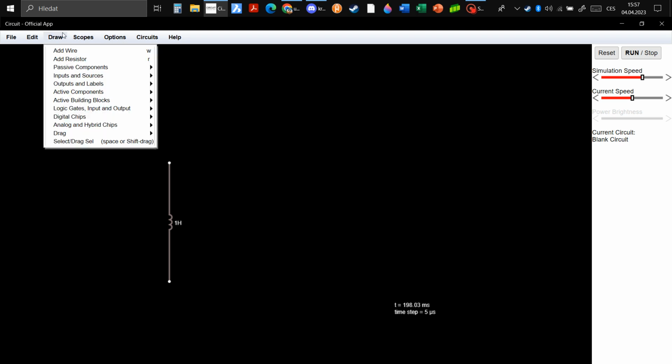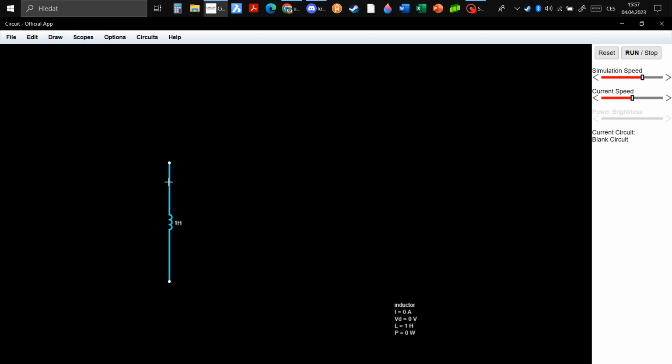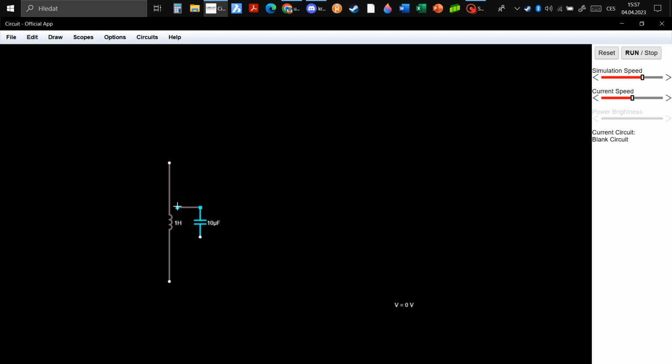So back to the thing. Let's say that this inductor has a power factor of 0.45, for example. And if we want to make the power factor better, we would take a capacitor and connect it across the inductor to make the power factor better. And by this, your power factor is suddenly much better at, for example, 0.915.